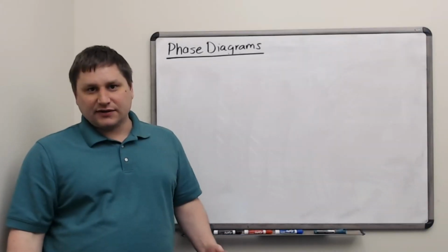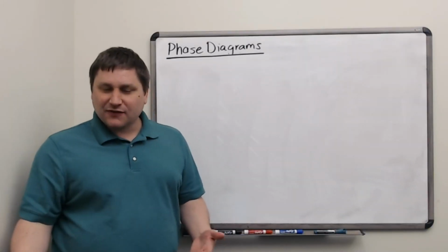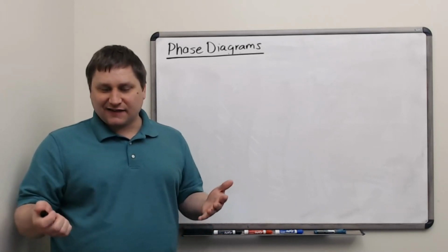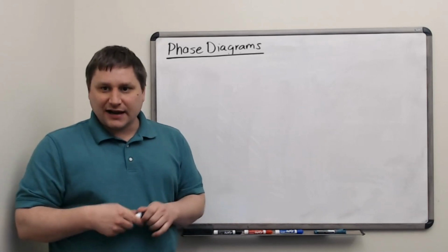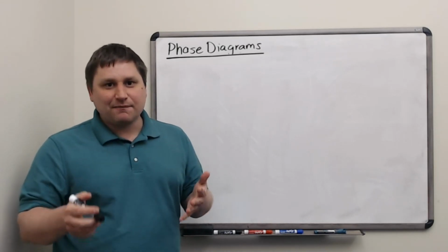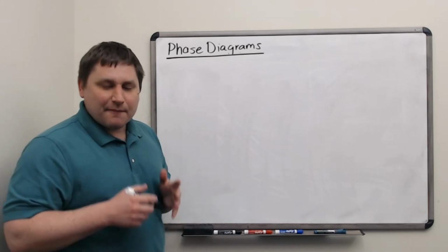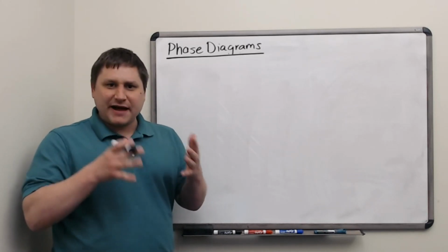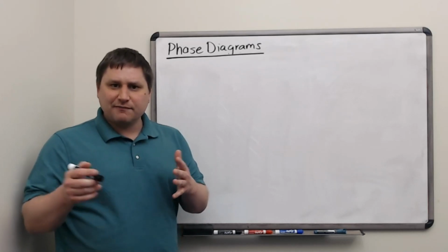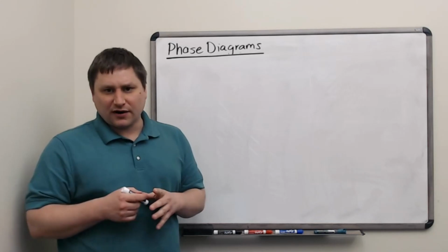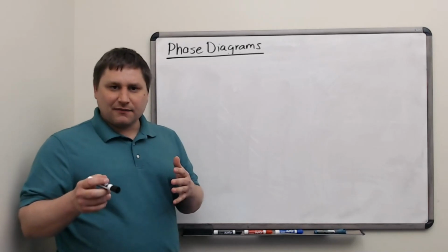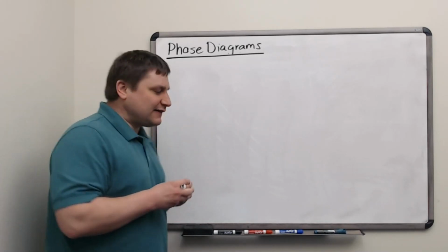Now that we've seen how to generate a phase diagram from a Gibbs free energy function, along with the concavity test, and whether a convex hull line can bridge across, let's look at the general types of phase diagrams that we could possibly encounter. Most mixtures of, say, a metal with two components as an alloy, or a solution of two liquids, or even a solution of salt and water, will have rather complicated phase diagrams, but they can always be made up of a few simple pieces. Let's see what those are.